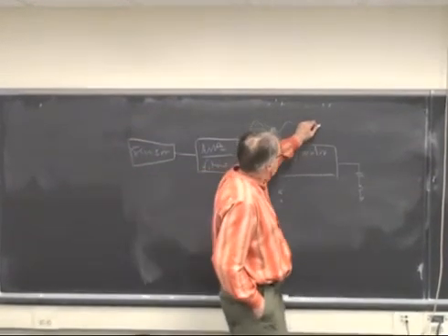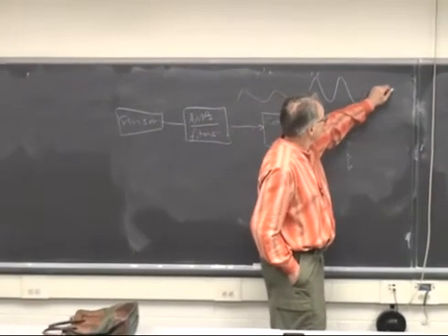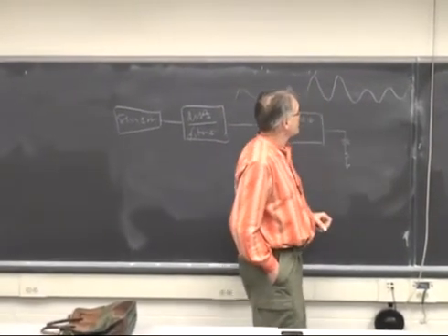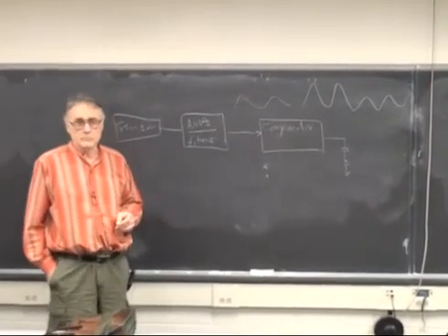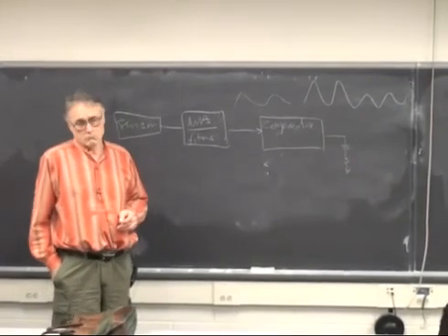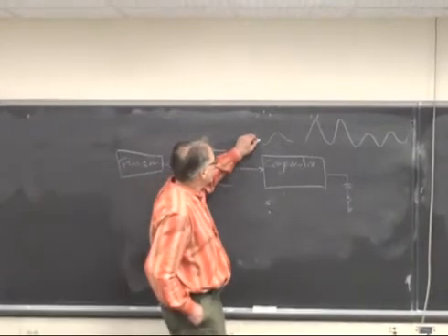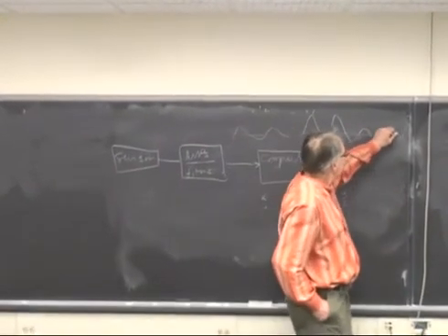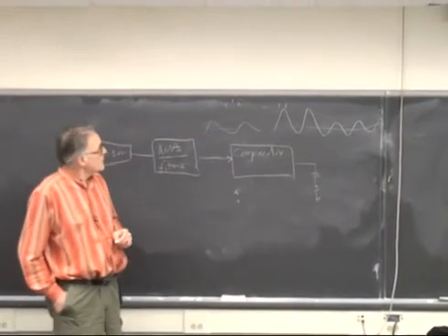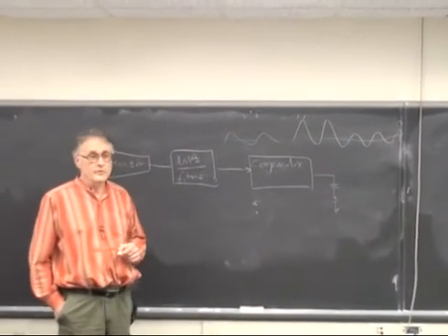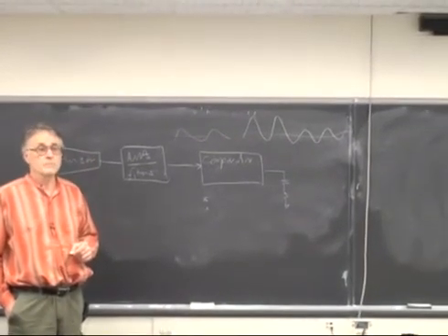Now this signal is going to vary quite considerably depending on the geometry of your finger and how you happen to be breathing. So what is the appropriate threshold for this? Some mean of the signal, right? It's some line that goes through like that. Oh, well that looks like a low-pass filtered version of the signal, right?